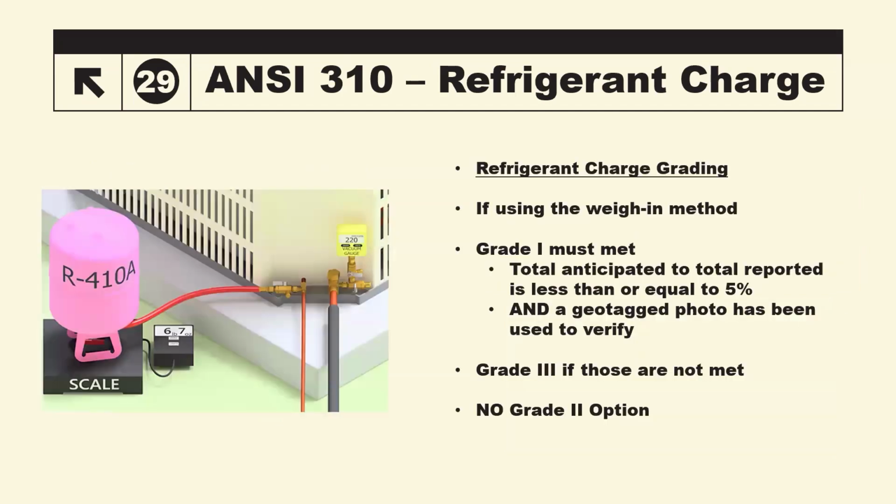And then, of course, the last method we have is the weigh-in method. So the rater is using data from the HVAC startup tech. From the documentation that's included, what we need is the total weight added and or removed by the tech.